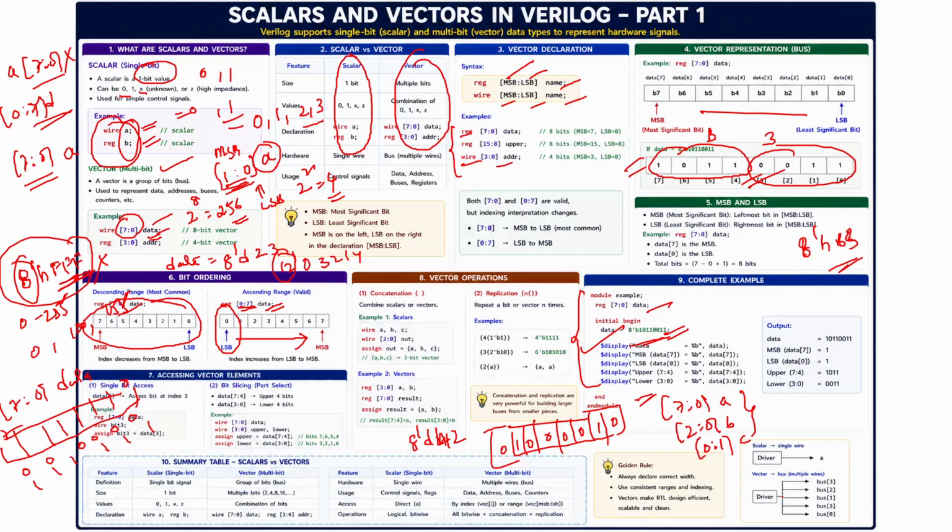Clear? See, these are the drivers. This driver is A, so I told you this is driving A. Similarly y equal to A I am assigning, and then without any delay y equal to B I am assigning, so then my driver will get a conflict. Which one do I want to drive, A or B? That's the driver conflict.